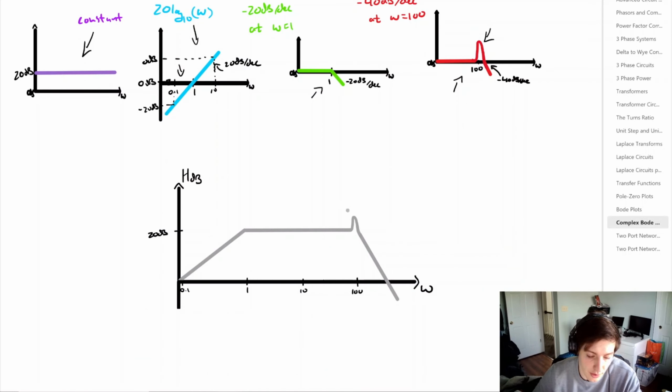Now, like it was brought up in the first part of this video, not all transfer functions are easy to work with or easy to force into forms that are easy to work with. Sometimes you just get a really nasty transfer function that you have to plug into MATLAB or something similar and actually see the frequency response. That's just the way it can be sometimes. But if you can force it into functions, you can see the behavior pretty quickly and see what's going on.